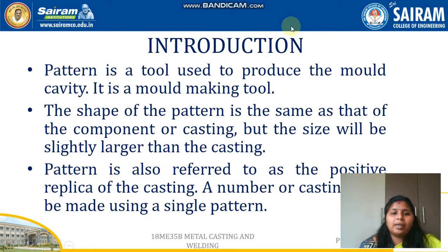The pattern is a tool to produce the mold cavity. It is a mold making tool. Whatever component we are going to produce, whether it is an engine block or a simple cube, we should first have that pattern, the replica of the component that we are going to produce.